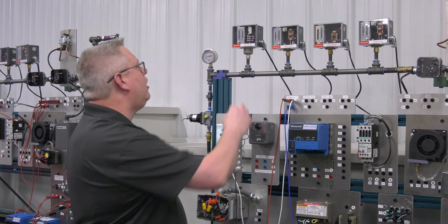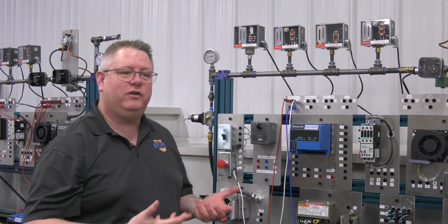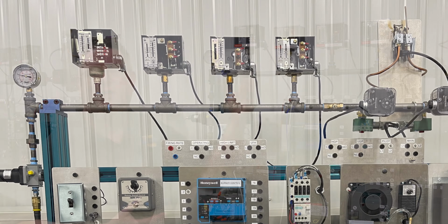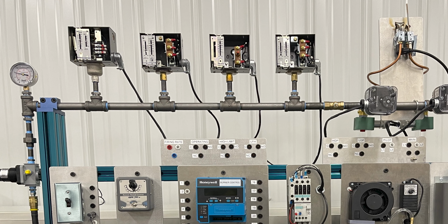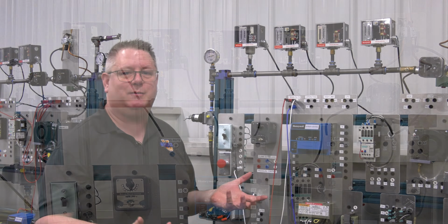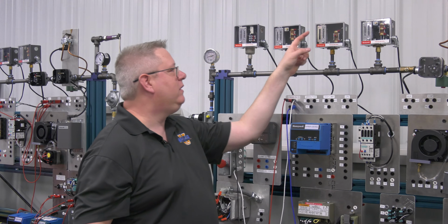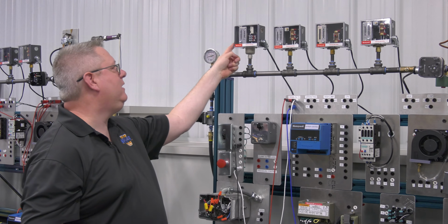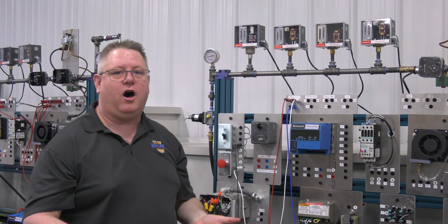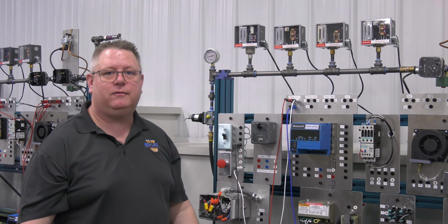So if I were to get a Sharpie and just write on the front of those, I would know exactly which was which, except it's a common oversight, those covers all come off. So if you remove all those during an inspection to unwire and remove and clean them, etc., you've lost that valuable bit of information. So if you're going to label these, I recommend putting the label on the metal side of the switch, so that even if we take the cover off in the future, we still have the identifying marks on each device.